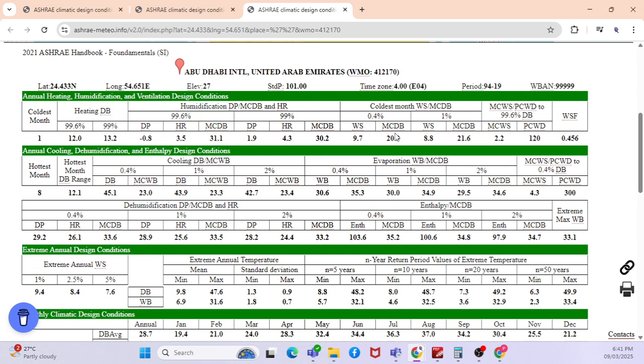You are an HVAC engineer, so you should understand what the outside condition is. Then only you can bring it to the design condition, right? For example, you are in the bedroom. What is human comfort? What is the design condition? 24, 25 degrees Celsius. Yeah, 24 degrees Celsius and 50% RH. That is human comfort, correct? Okay, now you should know what the outside condition is. Then only you can bring it to the design condition, right?